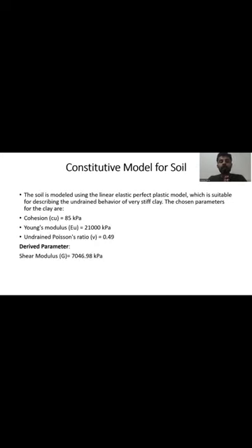The constitutive model for the soil is a linear elastic, perfectly plastic model, which is suitable for describing the undrained behavior of stiff clay. The chosen parameters were these. The undrained Poisson ratio was 0.49, so we derived the shear modulus, which is being given.